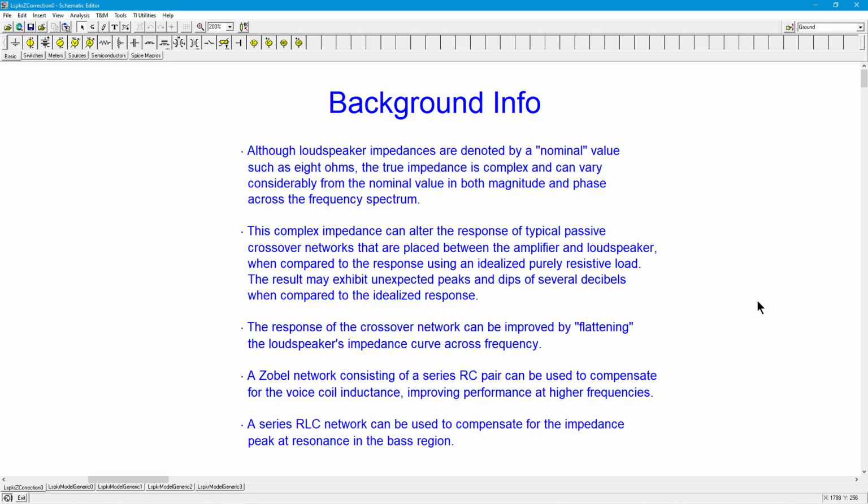Well, basically because it will interact with a passive crossover that you would use ahead of the driver. So when, let's say, a two-way system, you're going to have a woofer and a tweeter. A three-way, you'll also have a mid-range in there. But you're going to need some manner of splitting the frequency spectrum up. In other words, directing the content in those frequency ranges to the specific driver. That's the job of the crossover. Crossovers can be fairly simple, first-order units, second-order, third-order. They can be much more complex.